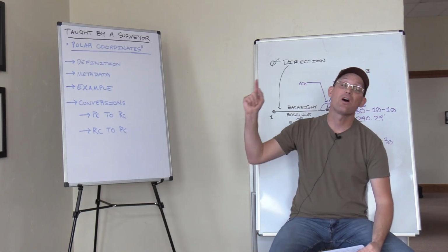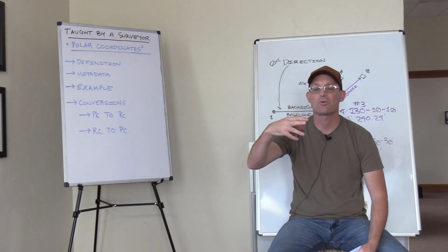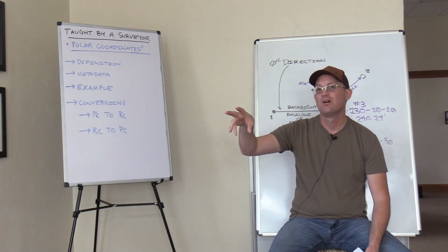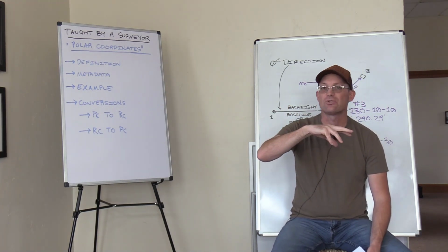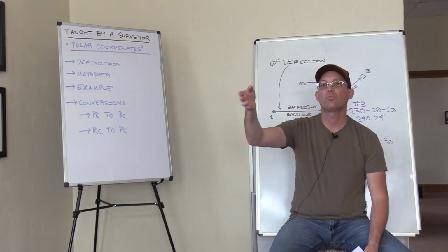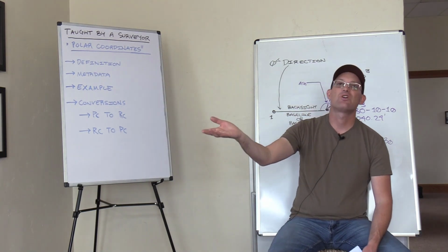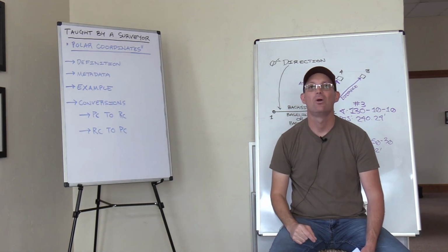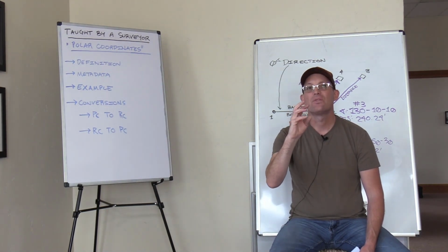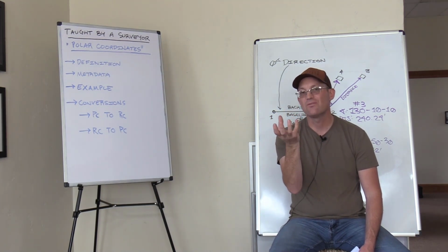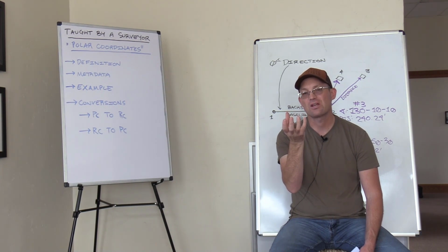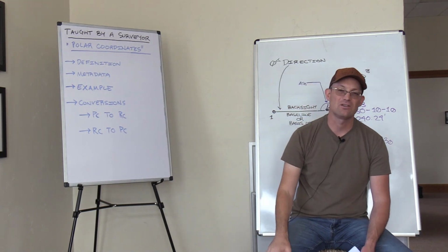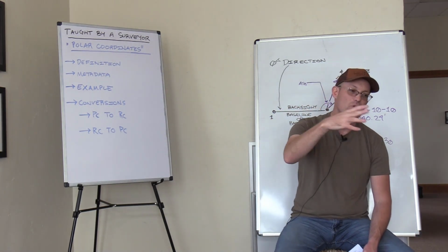Now, we also go the other way. We don't do that as much where I work because of the type of work we do, but you also go the other way. So if you want to take 2D rectangular coordinates from a drawing, like an engineering drawing or a construction drawing, and go mark those out in the field with the total station, you actually have to convert back to polar coordinates, angles and distances, because that's what a total station works with. Now, we don't typically do that by hand. You give the software inside the total station the 2D rectangular coordinates, and it does the math on the instrument to calculate the angle and distance that you need to locate the point from anywhere you're set up on the job.